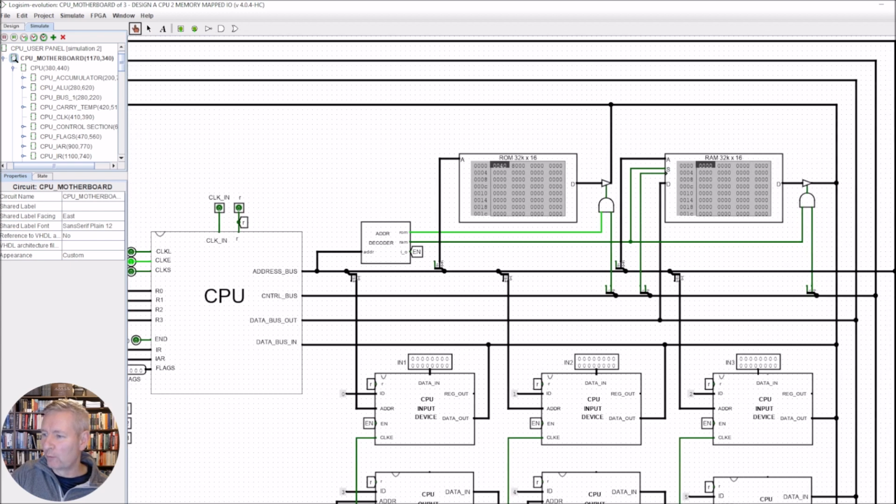The only information the ROM's going to have at the moment is where the program is held. So the ROM is going to be just a jump command. The jump command is 0040, and it's going to tell you to jump to address 8000. So whenever we get to this point, it'll jump to that address.